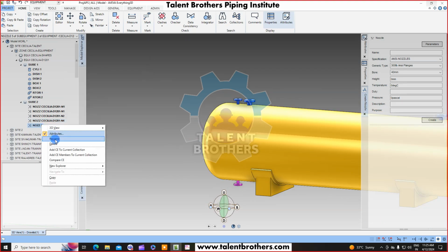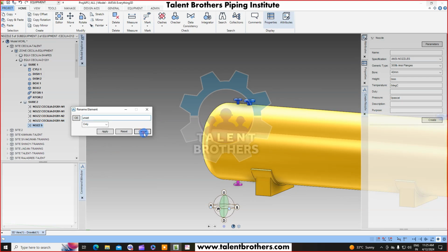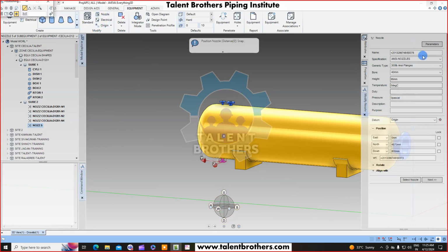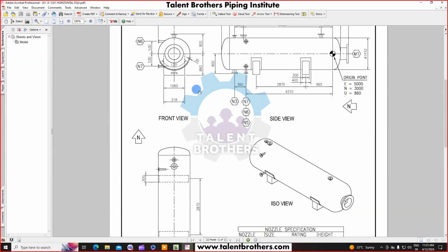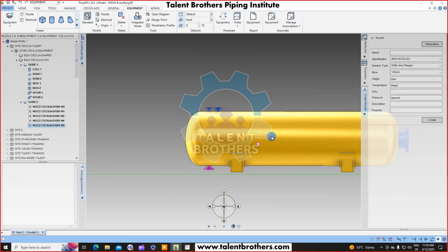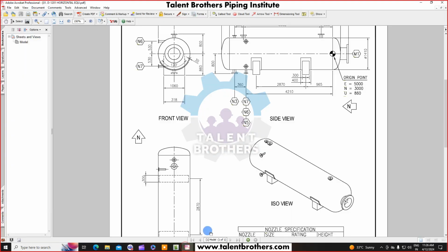Now you modify the nozzle properties. You change the name, or else if we want to change from nozzle modify, we can give the name there also. Equipment, modify and nozzle, and change the name here, and the nozzle name is N3, and enter it, and this is a dimension of 100. Now the remaining everything is same, and height also should be same. Height also 800, so same, so 95 mm only. Just leave it and go to the next. So properly it will be down inside.